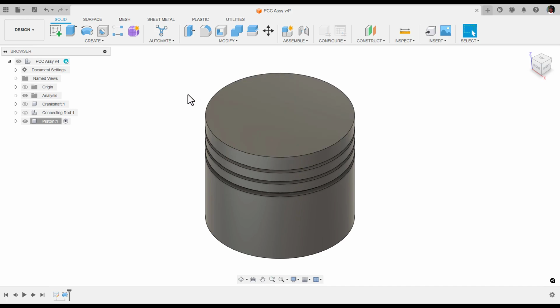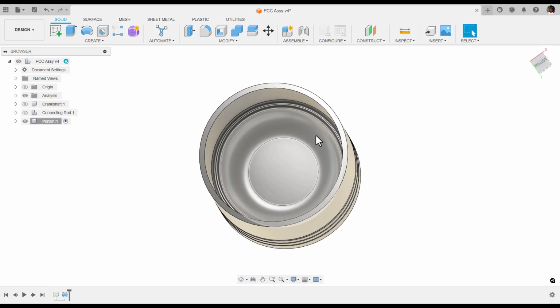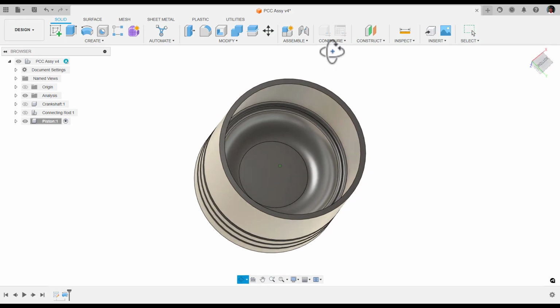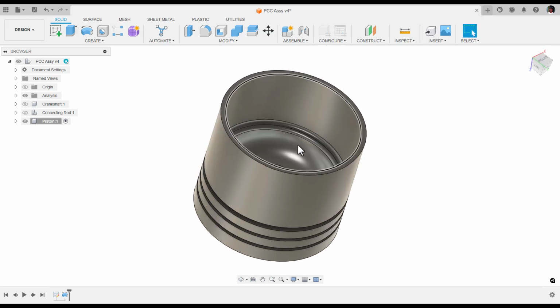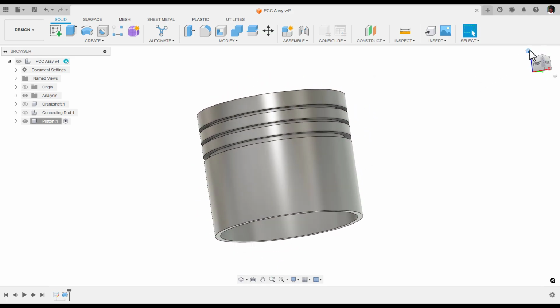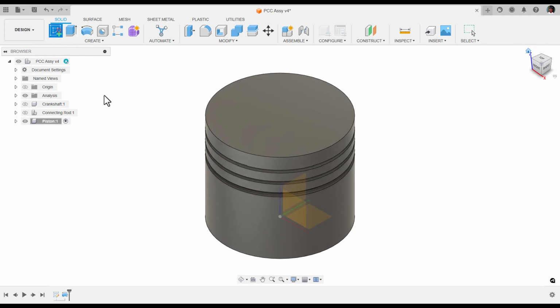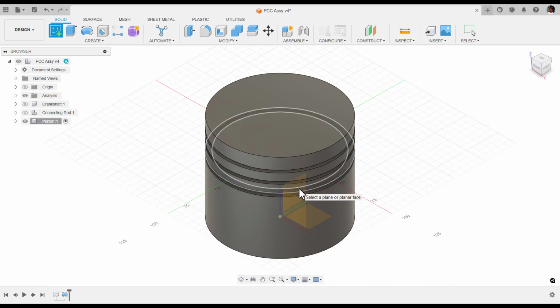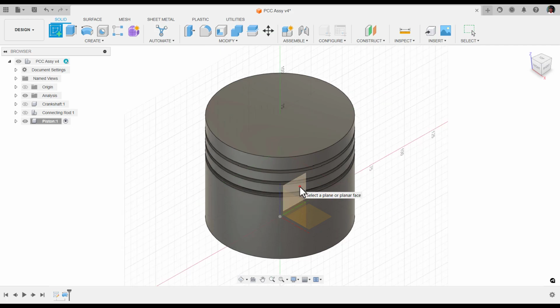Now we need to provide the rib over here. We will be having a crown pin or piston pin, right? For that we need to create the profile and extrude cut over here. Let's create that profile. Sketch. I'm going to select the YZ plane. If you are unable to select, hold the left mouse button and see the options. Pick the correct option, that is YZ.